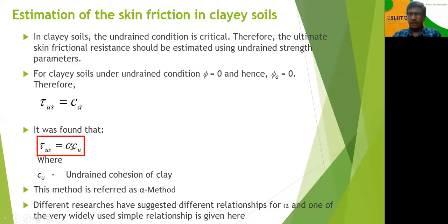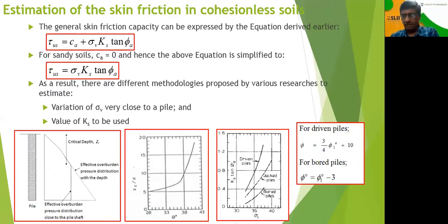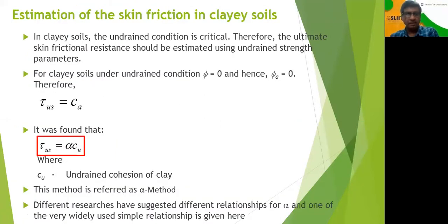There are many correlations developed by different researchers, but I will stick here with the method to determine the alpha value, that is the coefficient alpha, where alpha times Cu is the skin friction.